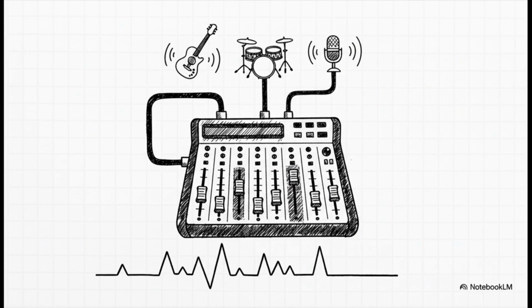That's Category 3. This is where procedures happen. Exam rooms, labor and delivery rooms. Losing power here could interrupt critical care. And Category 4 must be the highest risk. That's right. Category 4 is your ICUs, operating rooms, neonatal critical care. Any area where an electrical failure could mean immediate loss of life. That makes perfect sense. The math has to reflect that jump in risk from a waiting room to an ICU.